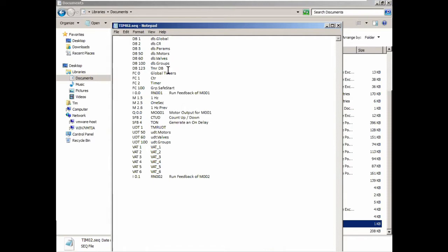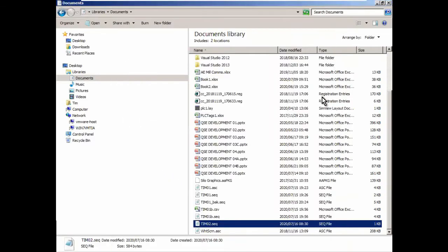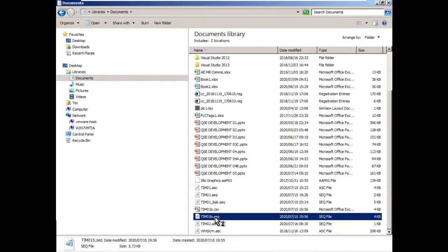So you can now pull this into Excel and put in all your symbols for all your I/O. Excel won't save it back as this type of file. You have to save it as a text file, then edit it in Notepad again to get it back to this tab format. A little bit laborious, but I've done that, and I'll show you what I did.